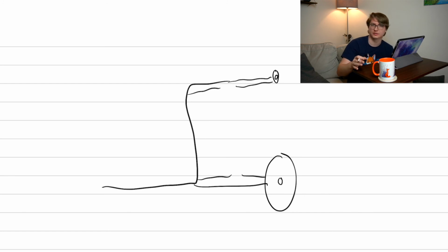Well, let's think about inductors for a moment. Inductors don't like quick change. Their resistance term goes as 2 pi f L. So the higher the frequency, the more it impedes it. It likes low frequencies. It doesn't like high frequencies. Imagine the signal that's coming by is a combination of a bunch of frequencies, really complicated, all combined together. What's going to act as a good low pass filter? By low pass, I mean it's letting the low frequencies pass through, not the high ones. So it's going to be an inductor. It likes the low frequencies. It doesn't like the high frequencies. It gets rid of them. It starts creating currents that oppose them. So if we wanted to get rid of the high frequencies, we would put an inductor down here.